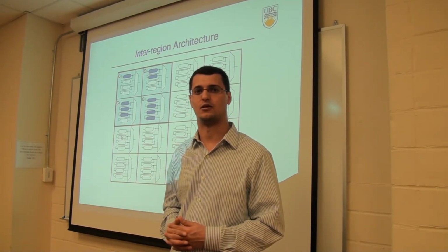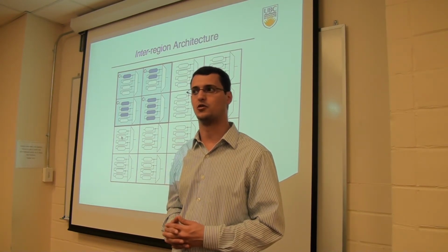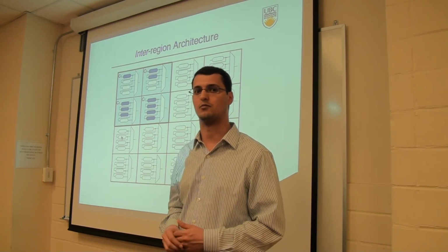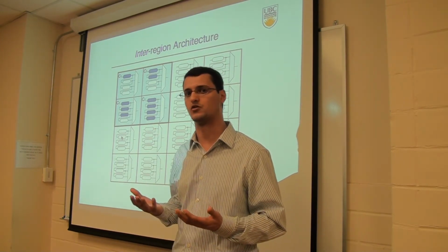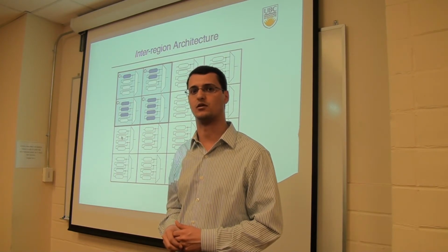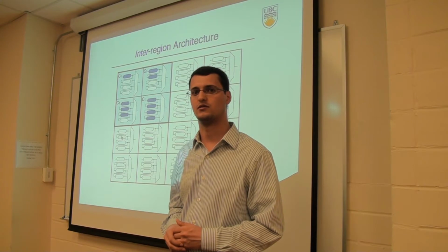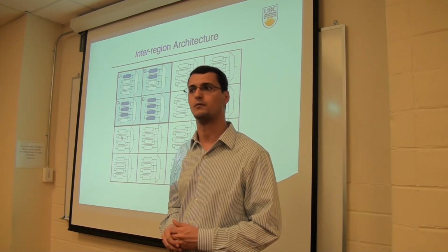So there's internal state that's stored in these power blocks. We power gate buffers, circuit components that can be power gated, but for memory elements we don't power gate these, to retain the state of the logic blocks. That includes flip-flops inside logic blocks? Yeah, yeah. Okay.